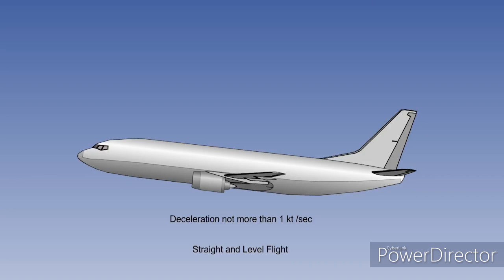This reference stall speed is the speed on which are based the recommended takeoff, maneuver, approach and landing speeds, which will give an adequate safety margin above the stall during normal operations. These are calculated as proportions of VSR: 1.05, 1.1, 1.2, 1.3 VSR, etc.